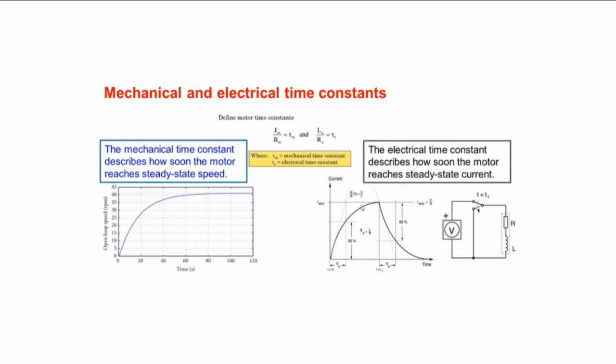If you want to define your electrical or motor constant, for example, in our commercial products, firstly we want to define motor parameters. Most important one, K_E, the back EMF constant. We connect a drill, slowly we try to turn it. Also we connect an oscilloscope or voltage meter, and then we observe it.